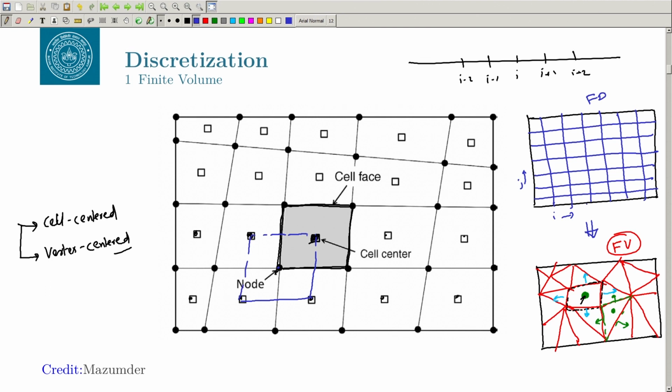That is just the way you do it. For example, if I take this structured grid, this could be my cell center. Here I have got the cell. This is my domain. Let us put very nice boundary conditions, so you have wall everywhere, and let us say the right top one is a moving wall, but still it is a wall. It is a moving wall which is moving in the right direction. In the cell centered approach, you have the values everywhere here, at the cell center. In the vertex centered approach, you will have values here, but you have to create a cell around that vertex. That is very, very important.